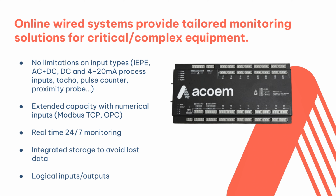There's also extended capacity with multiple inputs, so you can look at multiple parts of the machine simultaneously with an online monitored system. It can also take in protocols such as Modbus, OPC UA, Profinet, you name it, we can take that in. And then real-time 24/7 monitoring. So an online system is always on, always watching, always looking at the data. So it can trigger an alarm anytime an alarm changes or a condition changes or the speed changes to take data. There's also integrated storage in some of these so that if it loses access with its gateway or its server, it saves the data and it doesn't get lost.